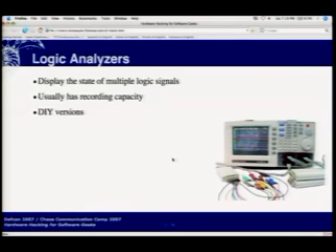You can make a do-it-yourself logic analyzer. I also have kits for that. I'm thinking since we have the question and answer room, I'll be giving some of these kits out there. They hook up to the parallel port and can watch 8 lines at once. Due to the relative slowness of the parallel port, they get about 1 million samples per second, so they can't pick up a signal much more than 1 megahertz. Well, actually it has to be much less than 1 megahertz.